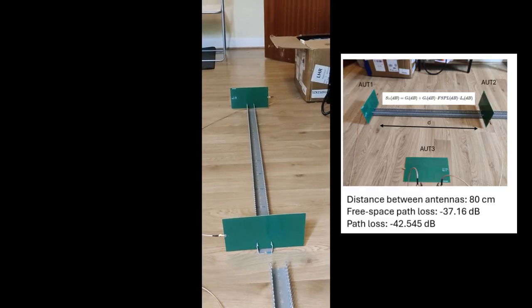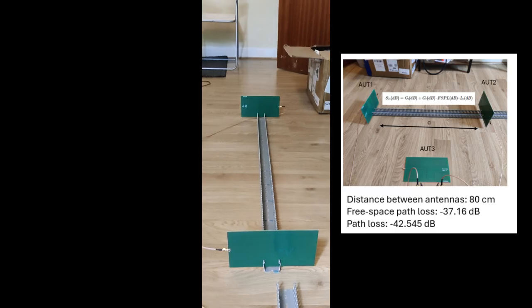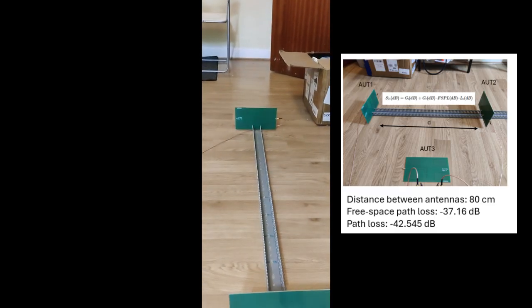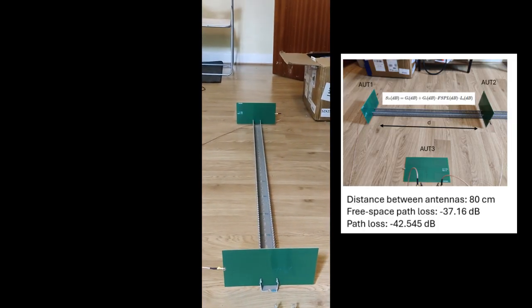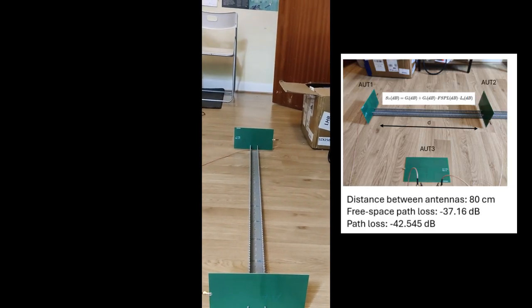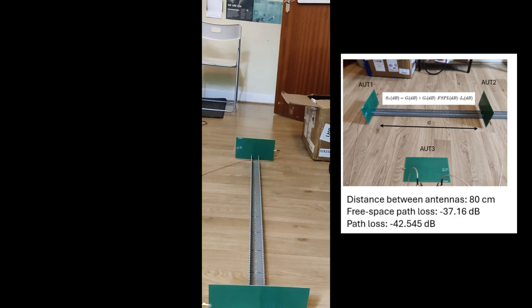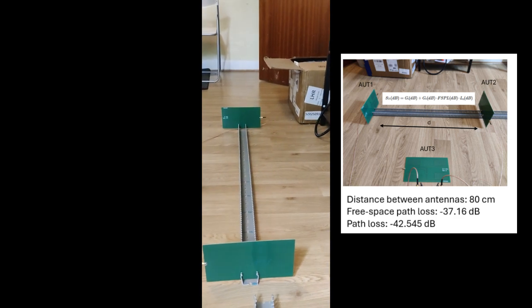To perform the 3 antenna test, the antennas must meet the Rayleigh criterion of the far field, which means the antennas must be spaced, in this situation, at least 80 centimeters away from each other. Second, the antennas must be aligned boresight to each other, and there must also be negligible proximity and multipath interference between the 2 antennas.